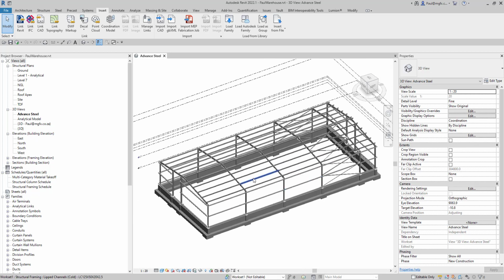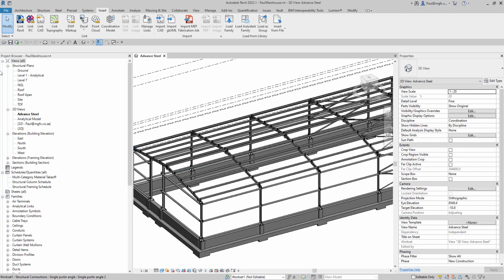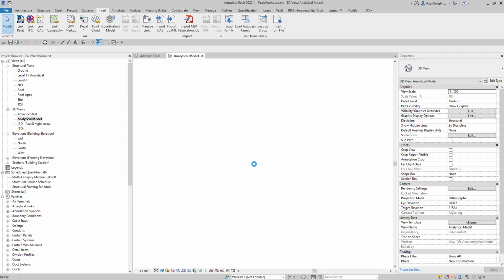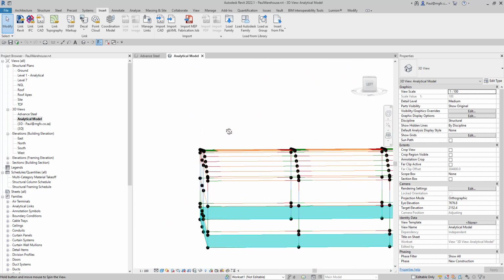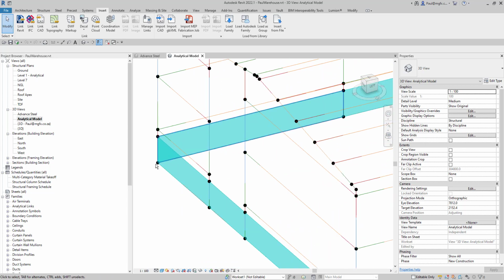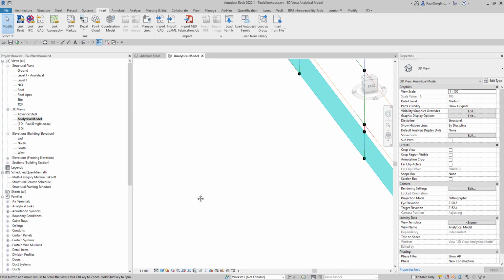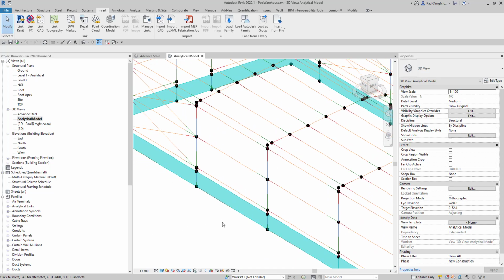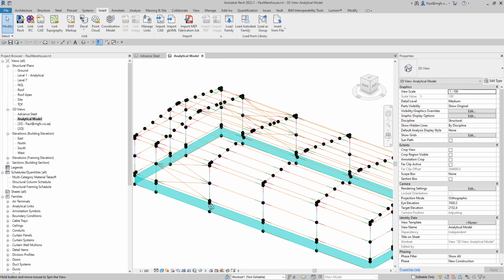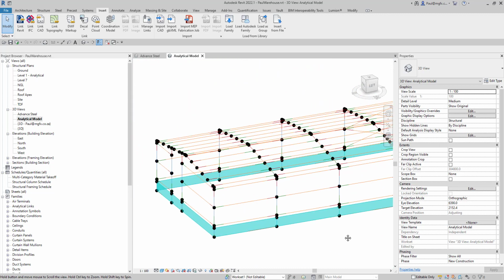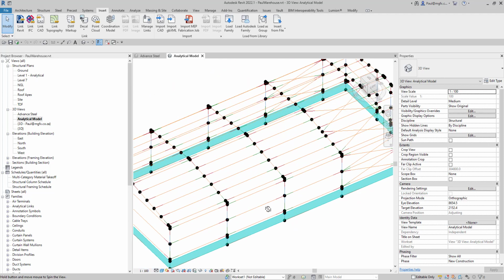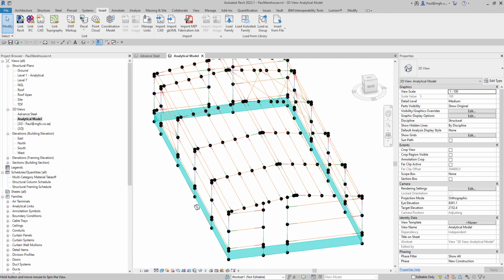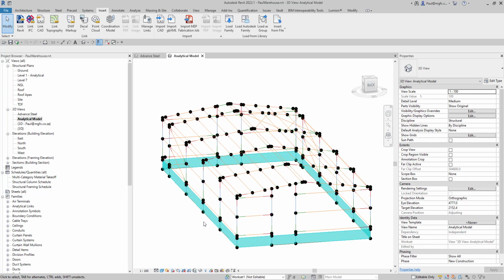Once that is done, of course, you must also go through the typical model checks to see that your analytical model at least looks good. This is a typical matchstick model that is set up, and hopefully when everything is set up correctly, you'll find that your nodes are correctly joined, and then your model will be correctly interpreted. In addition to that, you can also add some loads and load cases, but of course the analytical results will not be available until you do the analysis in Robot.